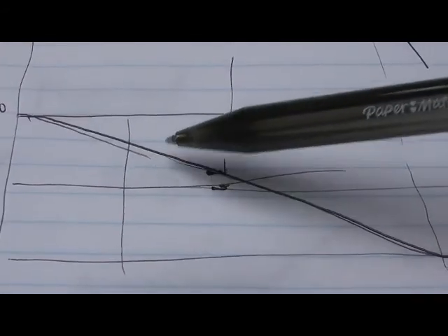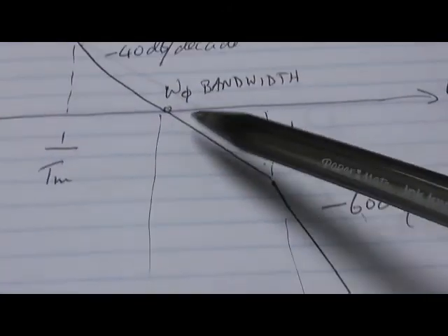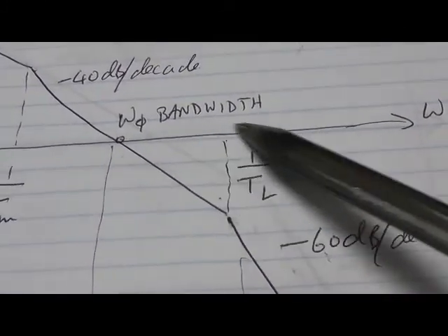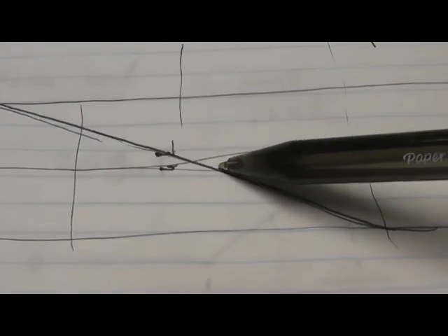If it was a lower bandwidth we might have a little bit of phase margin, but generally speaking, if you wanted any kind of speed of response, which means making the bandwidth here, the unity gain crossover, as high as we can, then we would pay for that by having instability. So it seems you can't have both at the moment anyway. So what do we do?